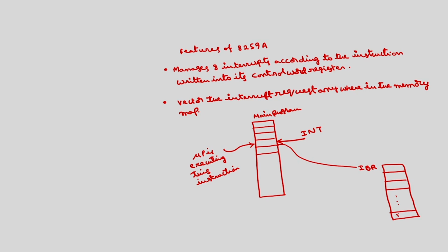The last instruction is IRET. It will pop the contents of the instruction pointer and come back to the instruction next to the one that was interrupted. This is called the interrupt service subroutine.